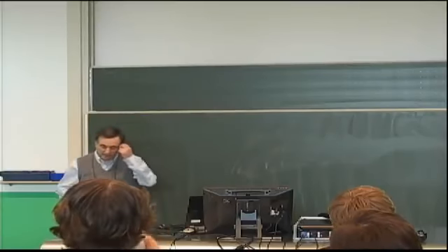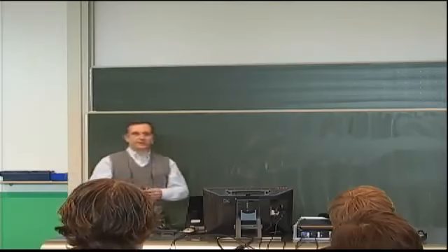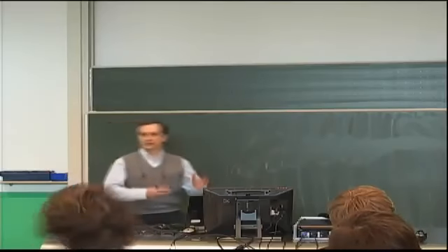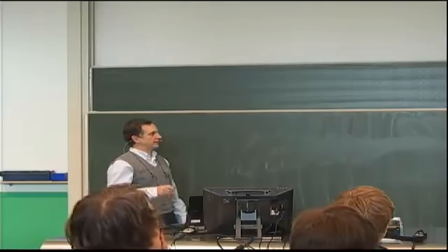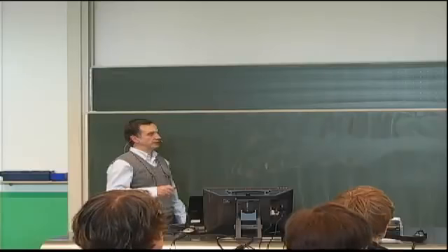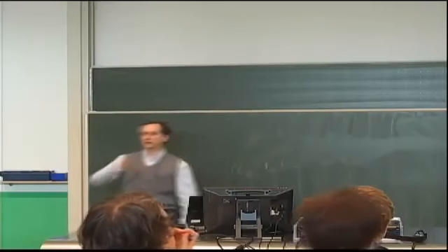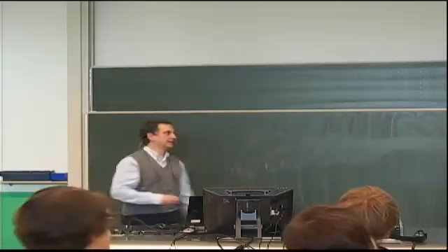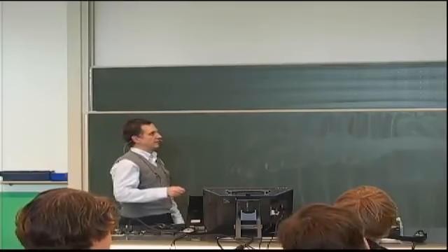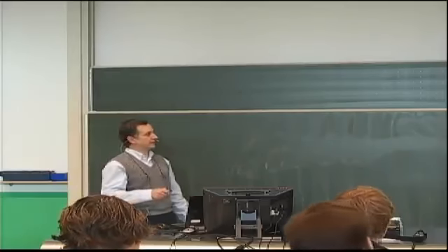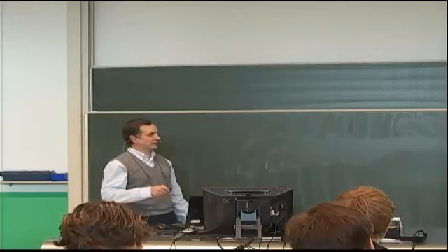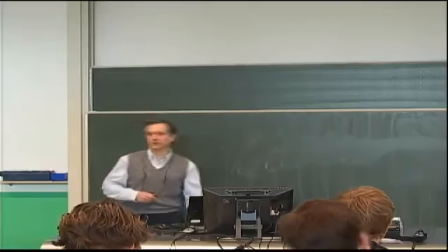And we said this one is a reasonably common situation relating to the stiffener termination problem, where stiffeners in plates adjacent to this one at the top here would be terminating here. So the load from each stiffener would have to find its way into the plate that is shown here. So it would end up being some kind of a very localized load. And that localized load would mean that the stresses would be relatively high in the region next to that point of action of that force.